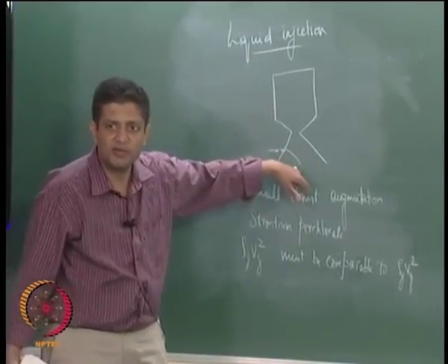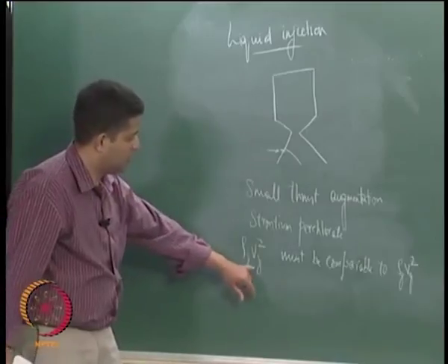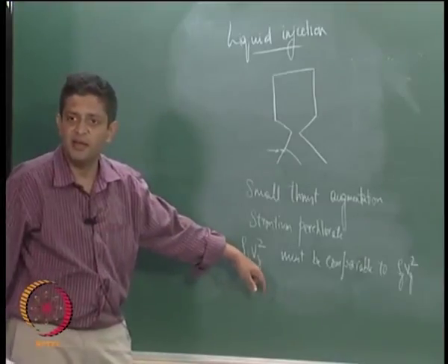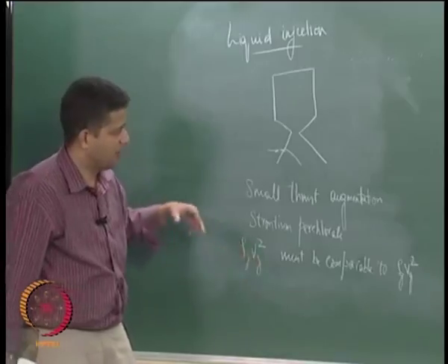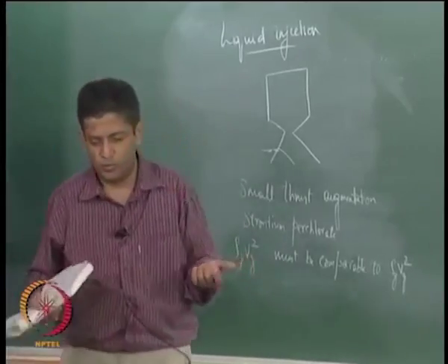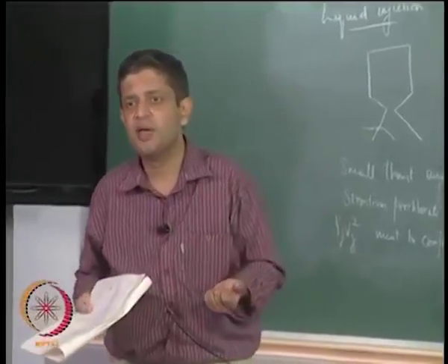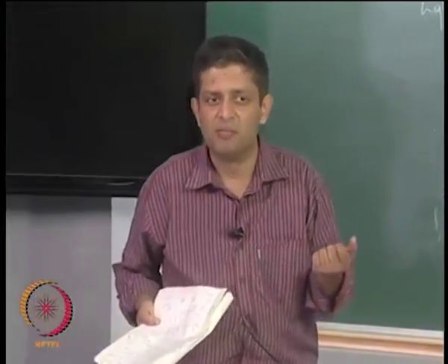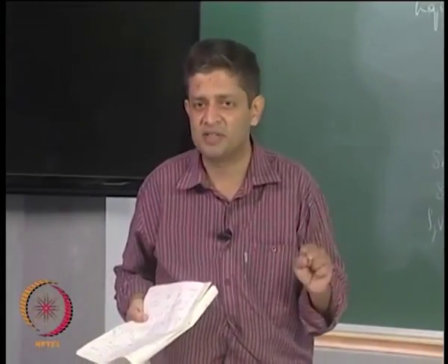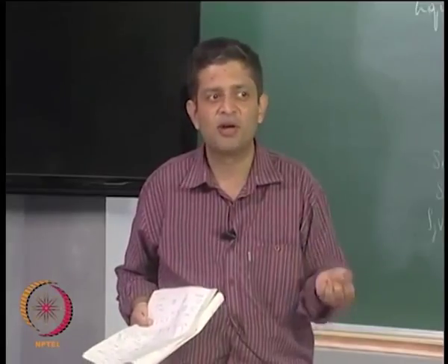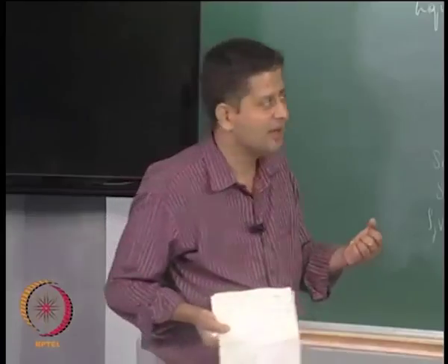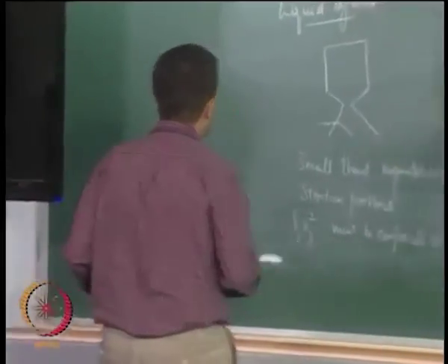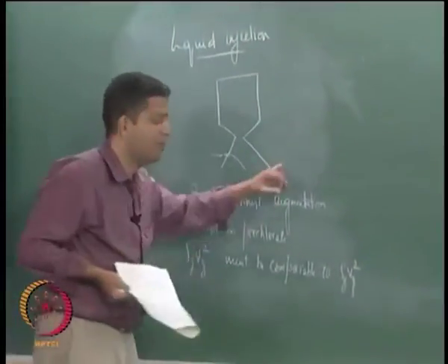That could also give you the required side force, primarily because you will have a very high jet velocity. Okay, and if you want to switch this off and on, it is not very difficult because you are only going to operate the liquids, right. Switching on and switching off a liquid rocket motor is not a problem, but this is something that has not been pursued and probably could be pursued sometime later.